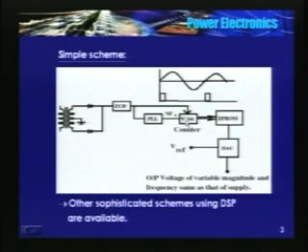So n could be here nothing but 2 to the power 9, that is 512, an n bit count. The digital data is converted to analog data using a DAC or digital to analog converter. Now we know that the magnitude of the sine wave is proportional to the voltage at the reference pin. So by changing V reference, I can change the magnitude of the modulating wave.